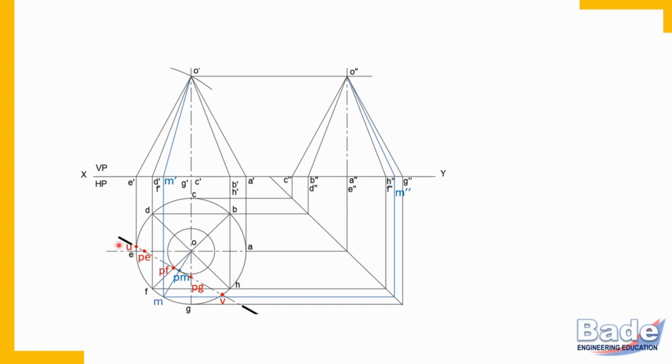For example, had it been a cutting plane inclined at an angle of 45 degrees, then we would have got that edge OF, or generator OF, perpendicular to the cutting plane line. So remember, in some of the problems on cones you may have a generator out of these 8 generators perpendicular to the cutting plane line, and then no extra construction using an extra generator is required.